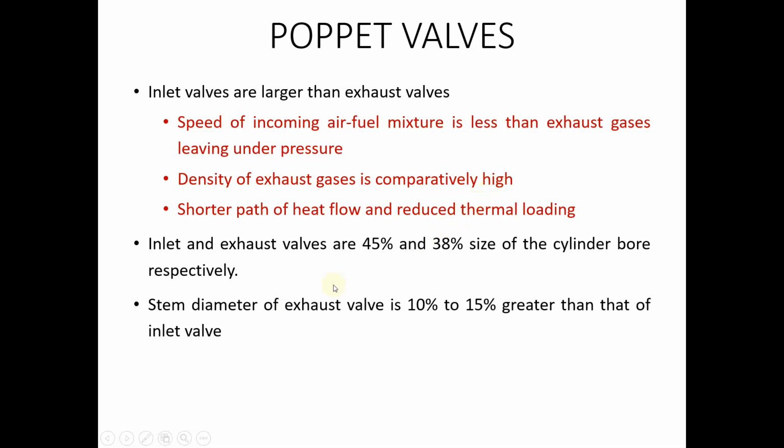So in order to prevent that, if we increase the stem diameter, we can prevent the damage to a certain extent. That is why the stem diameter of the exhaust valve is made larger.